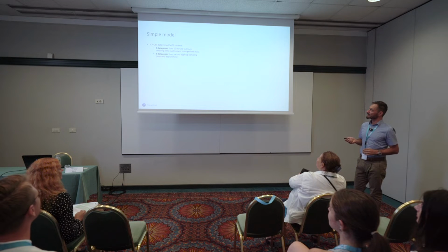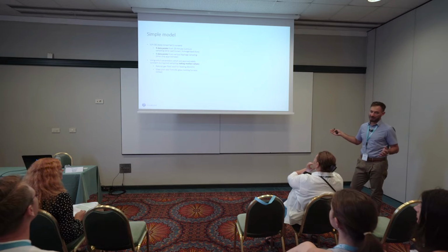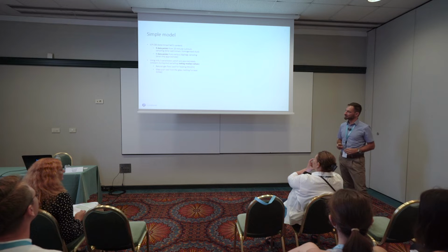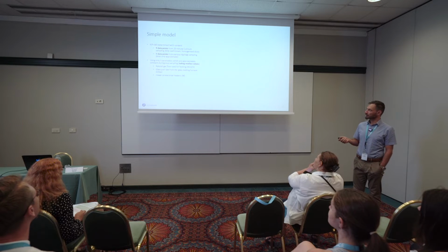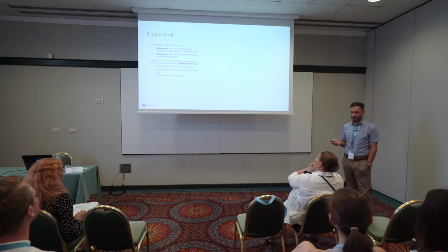And then based on these 9 data points from 20-minute sampling, from ICP-OES analysis, plus 5 data points from various big bag sampling, but with much less precision, we have created a simple mathematical model with only 3 parameters: natural gas flow, glass pull rate, and power on electrical heaters.